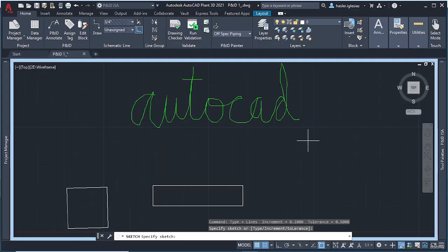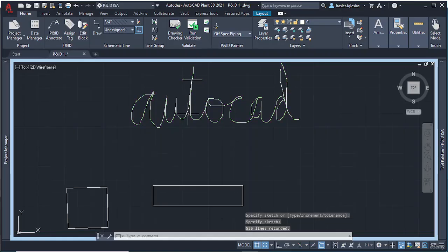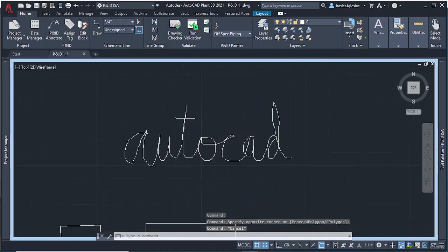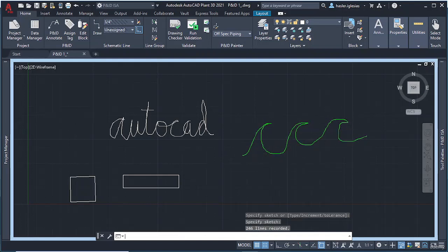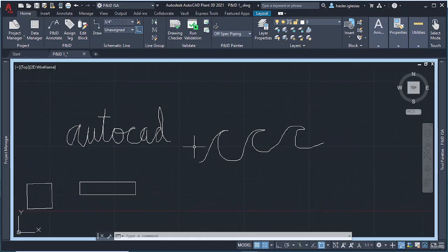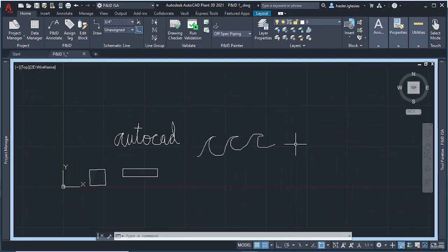So after I draw it, I just press enter, and now I have different objects of just what I drew. It's sometimes useful. For example, if I need something that looks like this, and I don't know how to generate that object, that I could with arcs and lines and circles and tangents, but let's say I don't want to get too stressed about that and I just want to draw it. I can do that with a sketch, okay?